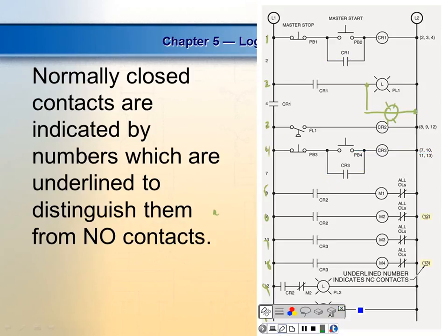Okay. So now I got line numbers. I've got cross-reference numbers. So now it makes the print easier to hook up. But I got to hook this thing up. Now in cars, what do they use to indicate the wires? They give them color codes. When you get out to a big plant, they don't use a lot of colors. Because if they got to buy a spool of red, a spool of green, a spool of black, a spool of orange, they don't like doing that. If you went to work out of U.S. Steel and you got into control circuit, you're going to find all black wire. So they use 1 gauge wire, because it's the control circuit, and they give it the same color.